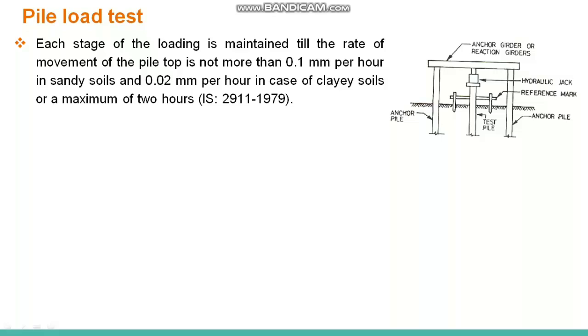Under each load increment, settlements are observed at 0.5, 1, 2, 4, 8, 12, 16, 20, and 60 minutes. The loading should be continued up to twice the safe load, at which the total settlement reaches a specified value. That I will show here.